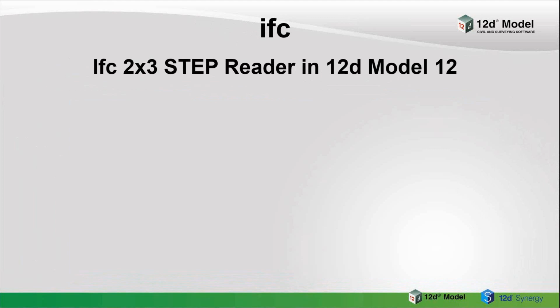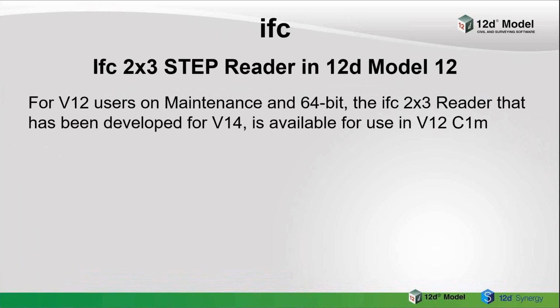For OpenBIM, what you're supposed to be using is IFC, the Industry Foundation Classes. That's the standard, so you're supposed to be moving away from proprietary formats, and we put that into version 12D Model 12 C1M, the STEP reader. I won't explain what all that is, but if you've got C1M and you're on maintenance, you will be able to read, not just produce IFC 2x3 files, but also read them in. So we brought that forward from version 14.